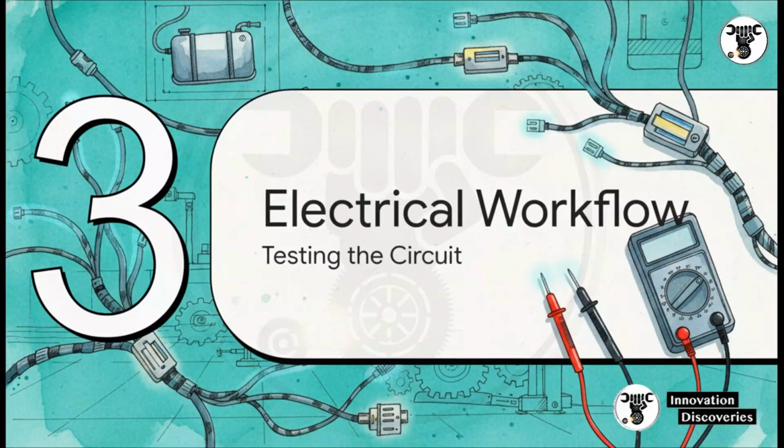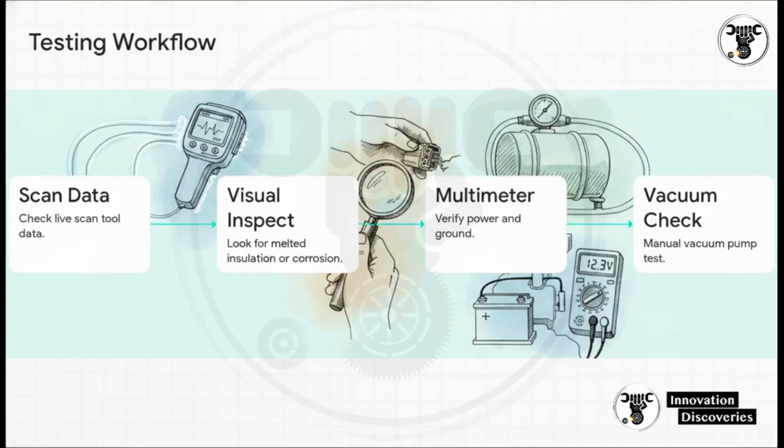Section 3. The electrical testing workflow. All right, this is where the real shop floor action happens. As professionals, we always test the electrical circuits before we ever condemn a part. Here is your exact chronological diagnostic workflow. You do not just start ripping out seats or dropping the fuel tank. First, we check live scan tool data. It's the least intrusive step.